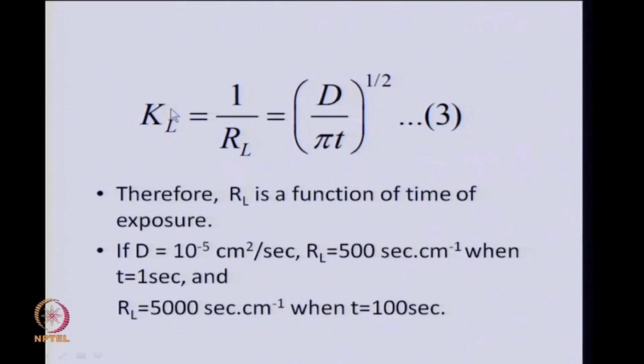Penetration model becomes a special case in this category when the lifetime becomes constant. In a general surface renewal theory, we will have a distribution of lifetimes of these elements or eddies from 0 to infinity. But for any surface renewal model where the surface is renewed by fresh liquid after certain intervals or whatever distribution, the dependence will come out to be same, K L proportional to root D.